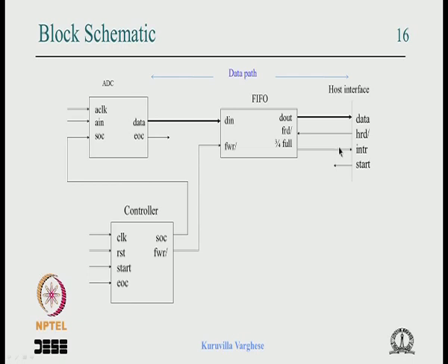So the question is that we are not giving any other handshake signal like empty or full to the host, keep it simple. So the one question is, when an interrupt comes, how much should the host read, okay. We are not sure, but we are sure that when the 3/4 comes, 75% is full.